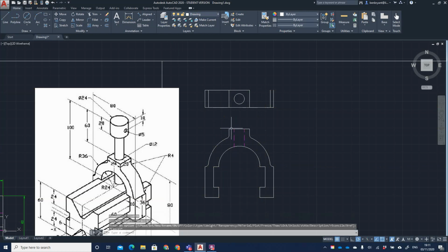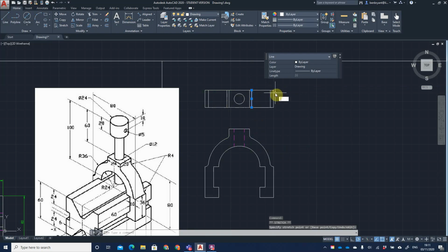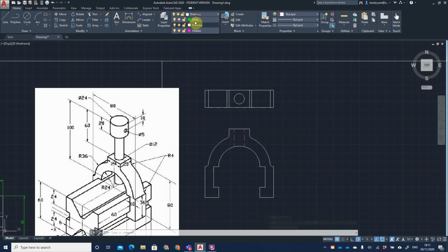But you could actually put another view running off of the base like so. Using the snap points, actually you'd probably see it more like this. So just one final one, going to close it off. Use the shrink or stretch command just to finalize that view. Hidden detail, this one, okay, obviously we would have some hidden detail replicating the lines running down. So again, you can either run a parallel line if you're happy doing so.